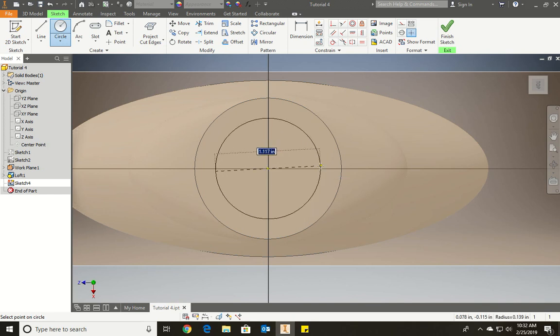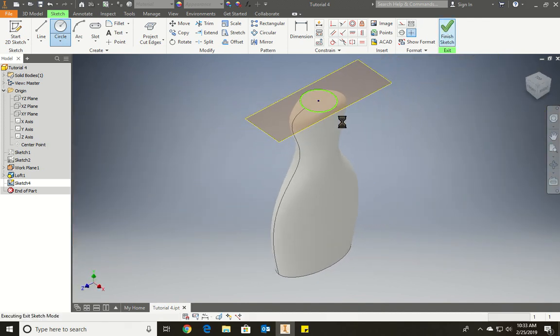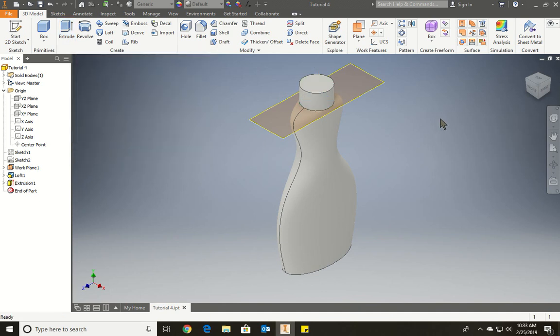From here, we're going to make it how big? Same as the other one. So if we click here, it should be 1.574. All right. If while you're making the last piece it didn't connect, when you do your circle, just click from the center until those two lines we made connect. All right. Once we have that circle, we press Finish. So now we have the circle again, and we can extrude it up 1 inch. So now we have a shape like so.